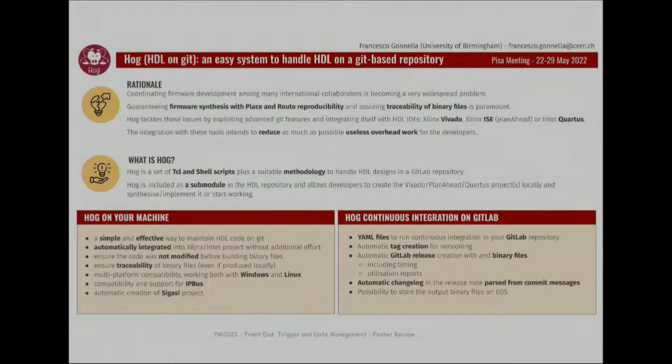Now more to the software side. This is an interesting tool, HDL on Git. It addresses the problem of firmware development in collaborations, the traceability of your firmware. It's based just on a set of Tcl and shell scripts, so minimal overhead, and has integration with various IDEs, so it seems like quite an interesting tool.